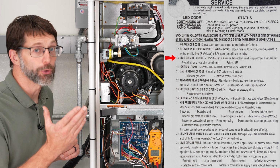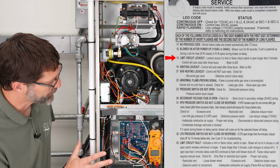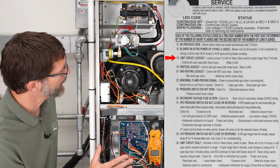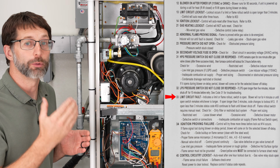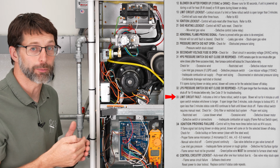Status code light number 13 is a limit circuit lockout, and that means that this furnace is not going to operate for say 3 hours, and then it's going to check again to see if the flame rollout switches or the thermal limit switch is now closed. And so basically it's going to go down to error code number 33 now, which is a limit circuit fault.